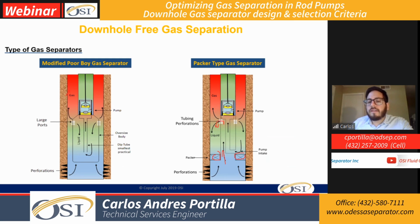Some of the gas is going to be released from right here. Some of the gas will start rising up, and then at the moment that the fluid starts flowing down, we will have gas bubbles just start rising up, increasing the separation efficiency using that ID of the casing. All right, so let's move on. That will be our gas separation, the main idea of each one of them.